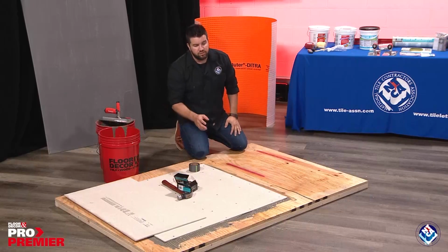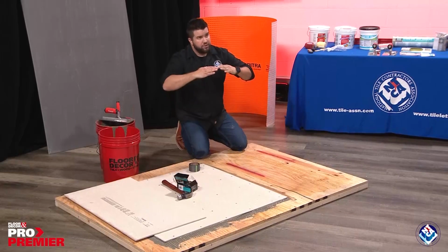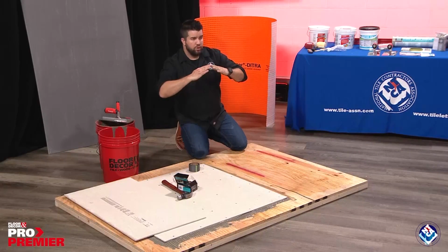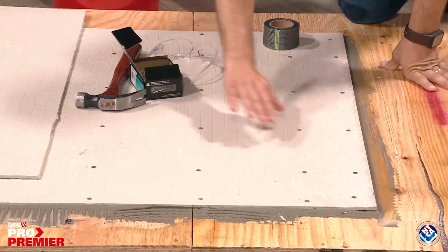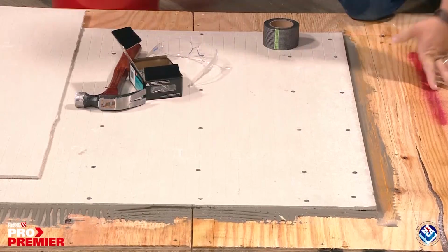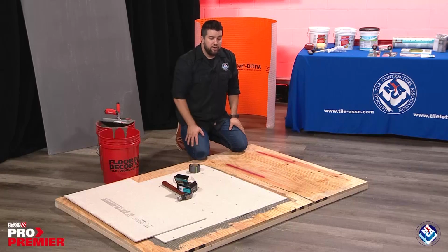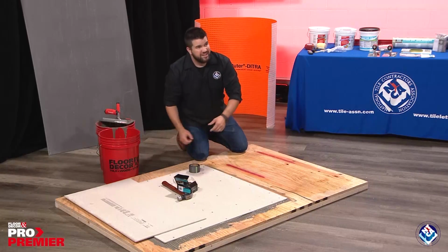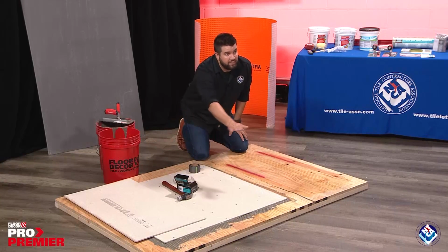Speaking of belt sanders, here's one other thing. I already mentioned this joint right here, but what if those joints had seen some weather before the roof went on the house? What if those joints had kind of tented up a little bit? What if we had a hump right here in the joints of the two pieces of plywood? Well, we would want to fix that before we start installing any backer board. So again, we could take a belt sander with some 40 grit sandpaper and flatten that subfloor out just a little bit.